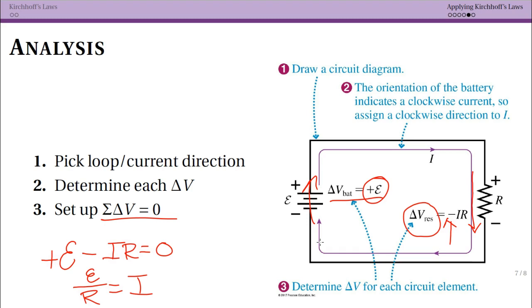So this might just look like Ohm's law to you, and it's really kind of a variation on Ohm's law, but it tells you that the current coming out of the battery depends on the EMF of the battery and the resistance, or the load, we frequently call this the load, of the circuit. So again, here we haven't gotten anything too special, but this will become more interesting and more complicated as we add more than 2 components to our circuit.